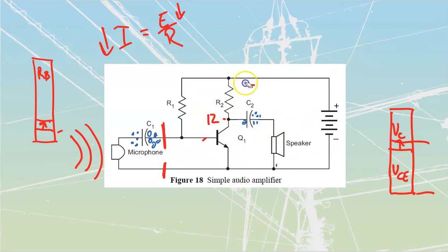Now, this circuit is not without problems. This circuit is actually screwed for an amplifier because we can't vary the amount of volts over top of here. We do need to have a resistor in line with that for us to actually be able to do that, because this is always going to maintain 0.7, which would mean that we would need to have an additional amount of volts that we would drop off here.